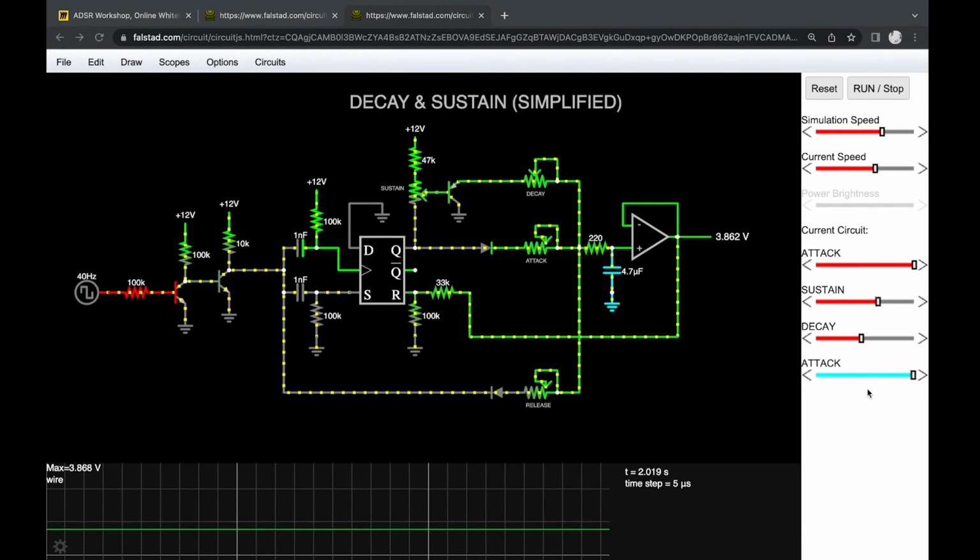All right. Anything else? Kash Garmin says, is there any place for linear pots in analog synth? Definitely there is, because sometimes, for example in my filter design, the pot that I use for the control voltage, like for the big cutoff knob, that's a linear one, because the filter itself reacts exponentially to a linear increase in control voltage. So you want the control voltage to be linear, actually, to have a smooth kind of cutoff sweep. So sometimes it makes sense.